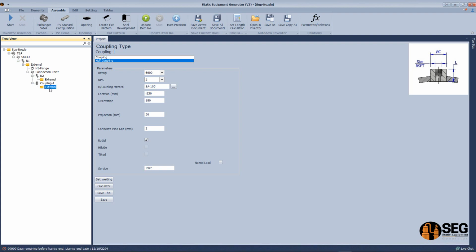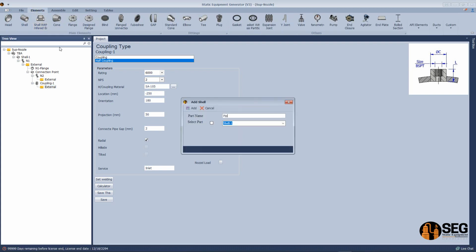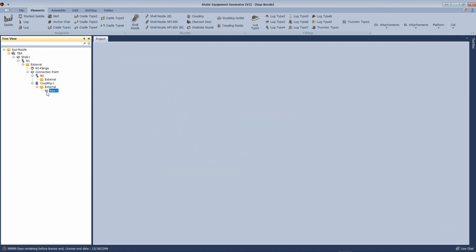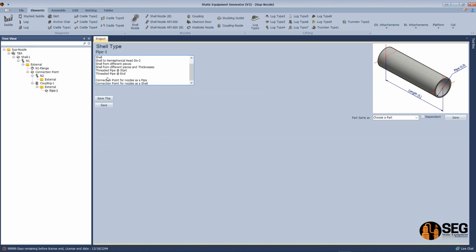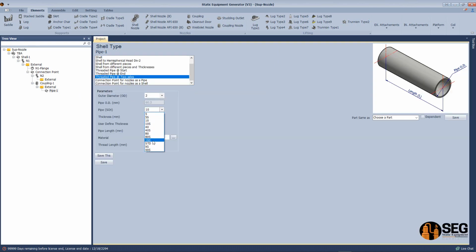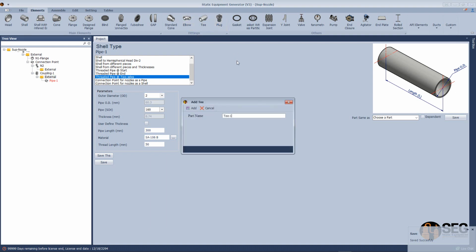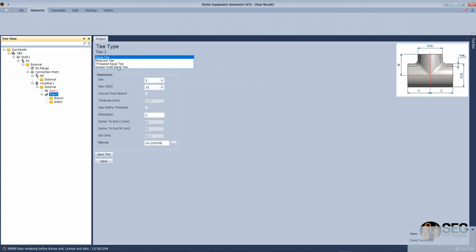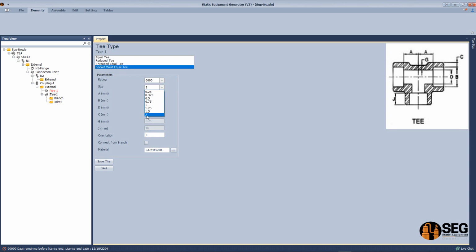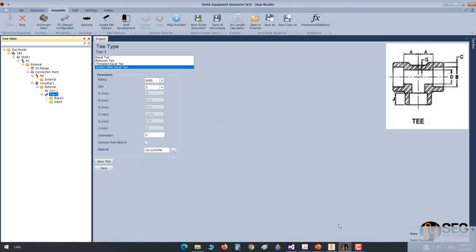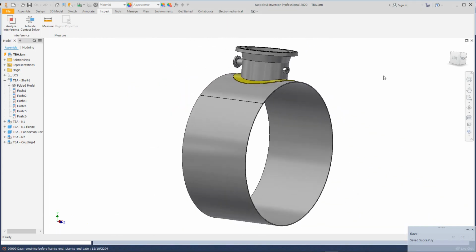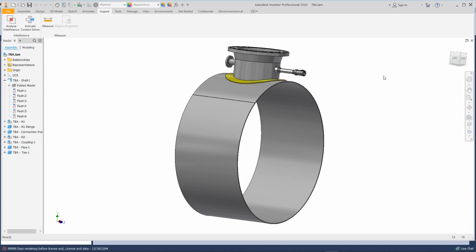For example, let's select this one, and from here let's select a pipe, and let's select this pipe as a threaded pipe from the two sides. So let's select this pipe, make it 2 inches, and set the length of this one and the thread length, and you could add other parts like a T, for example. And for this T, we will make it a socket weld T. Select the rating, size, and orientation, and if we click assembly, now you will get a connection for this coupling, a pipe connected to the coupling directly. After that, socket weld T, like that.